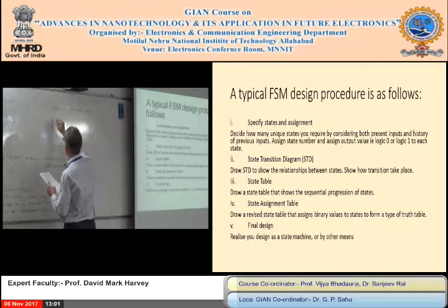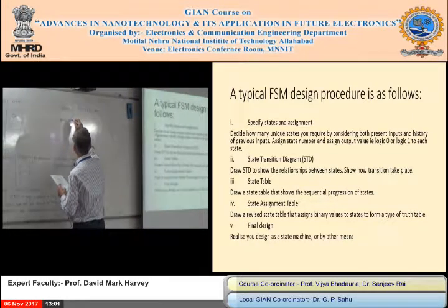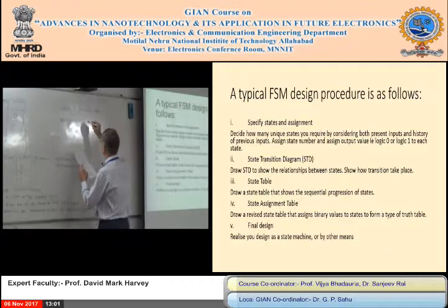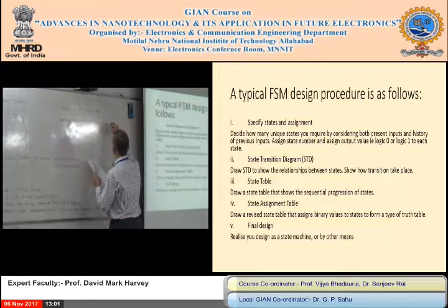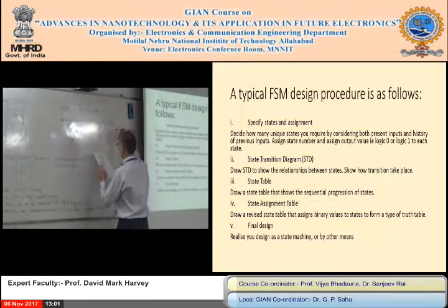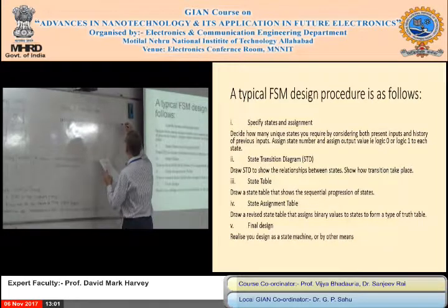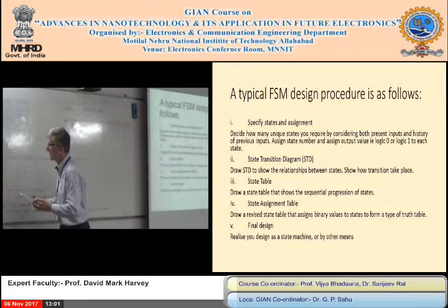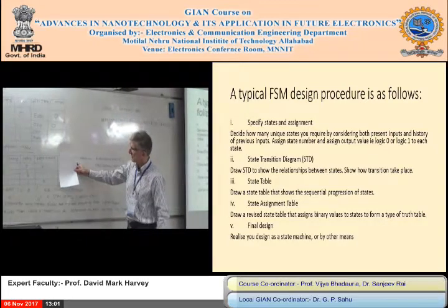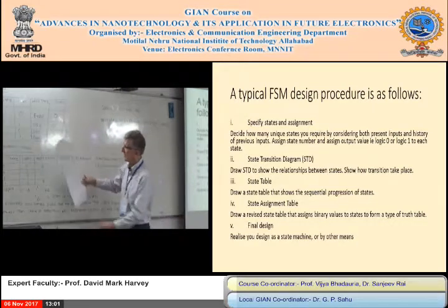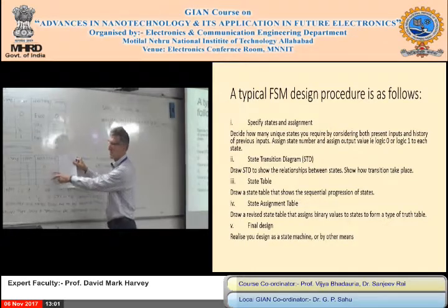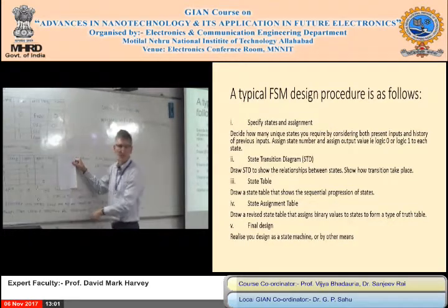The next stage. So if you look at this as a sort of truth table now, if you look at those two, that's the outputs and the inputs, put another line there, we can see this is the truth table for exclusive OR. When the inputs are different, we've got a 1, when the inputs are the same, we've got a 0.